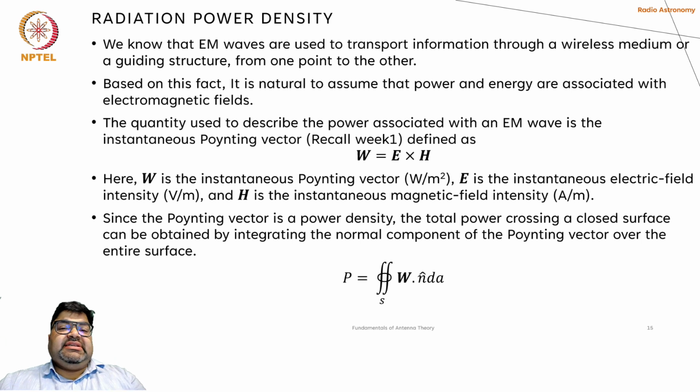For any given antenna, we first calculate the current density, then from there we get the magnetic vector potential, and from the vector potential we get H, the magnetic field. From H we get E, the electric field. Once we get the electric field and H, we can choose the right coordinate system which describes the system at hand.